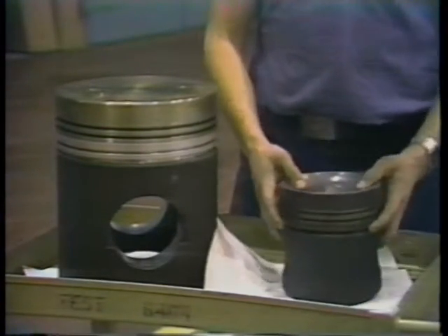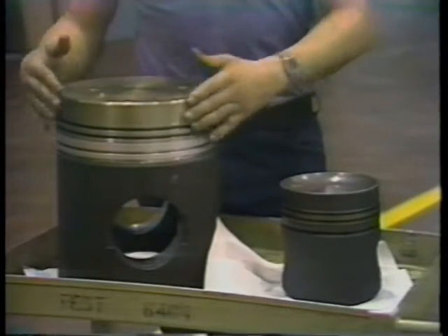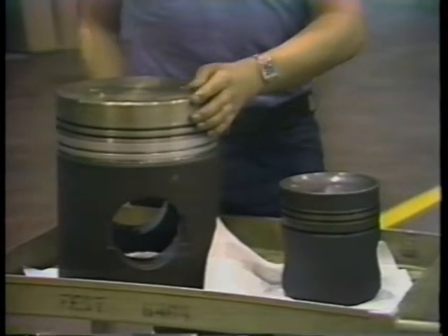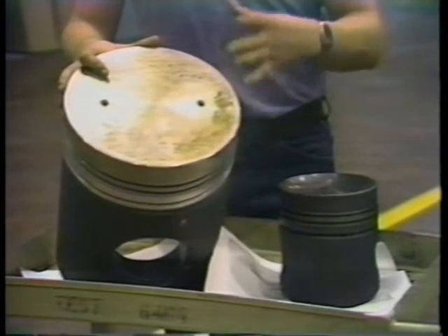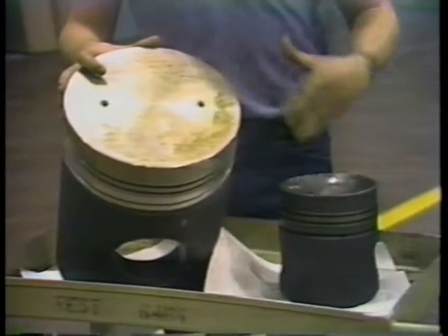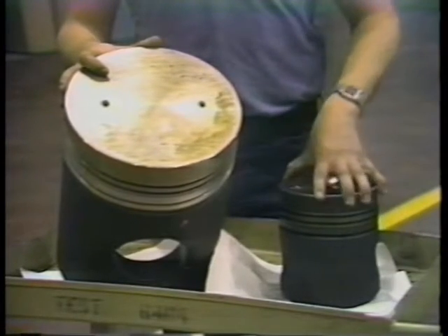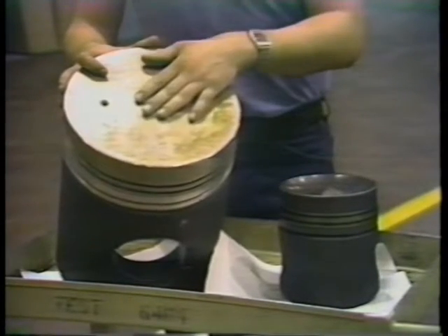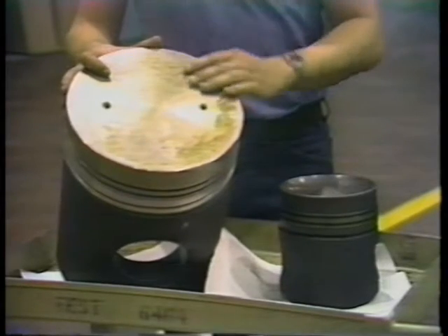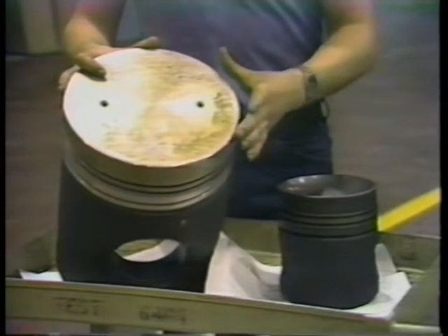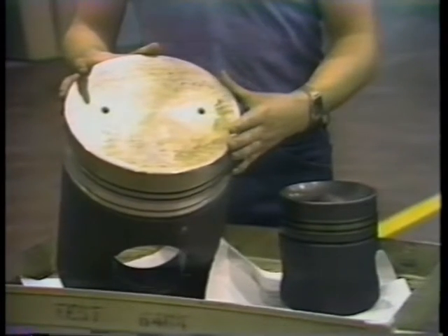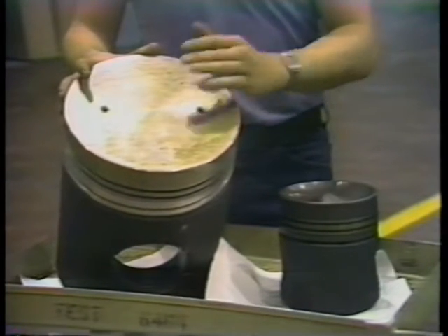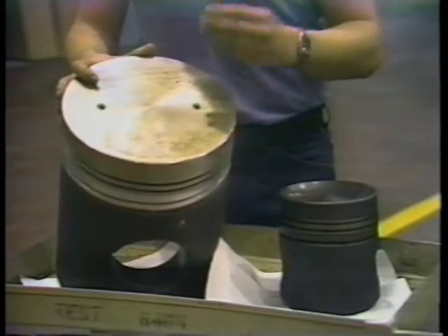So what we do is go to a larger engine with a larger piston, and this gives us more volume in the cylinder and gives us more power. This piston runs about 115 horsepower a jug. The engine that this piston goes in runs about 300 horsepower a jug. The reason is we have more volume and more fuel-air mixture driving the piston down. But we can do it this way without increasing effective compression ratios.